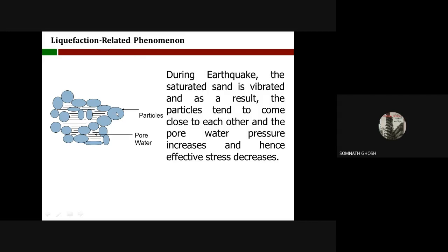Particles means it may be sand plus silt, like that. Basically sand is soil, and these interparticle gaps are filled up with pore water, basically water. During earthquake, the saturated sand is vibrated, and as a result, the particles tend to come close to each other. So if the water goes away, naturally it will be like this, right? And the pore pressure, water pressure increases, and hence the effective stress decreases.